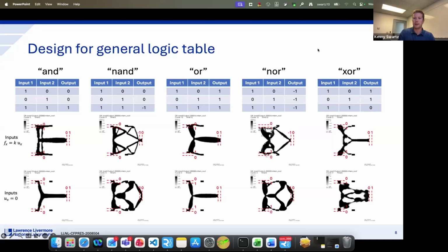So this is the exclusive OR. What we mean here is that we want to actuate if either input is flipped to its on position, but when they both are, we actually want to undo that and make sure that the output is not actuated. And I think the way that it does this is quite clever in that there's basically this middle region that really stretches out only when both inputs are actuated. It's maybe more clear at the bottom here. So if one flips it over, two flips it over, but then they both go, and it actually just opens up this middle and avoids pushing the output to the right. So this is a gate that at least I would not have been able to come up with a mechanism for. I wouldn't have been able to design this one on my own in a way that worked. I think it's cool that the optimization could find this solution.